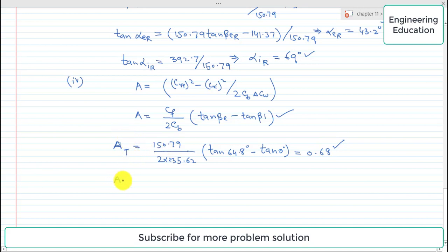Now to find the value of degree of reaction at the root, again this expression will be used with subscript R: 150.79 divided by 2 into the blade velocity at the root, which is 141.37, into tangent beta ER, beta ER is 61.9 degree, minus tangent beta IR, beta IR is 59 degree.